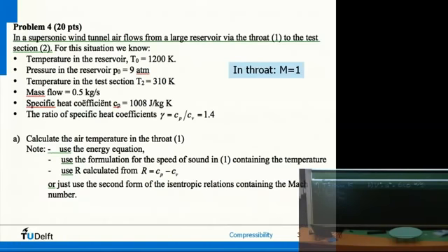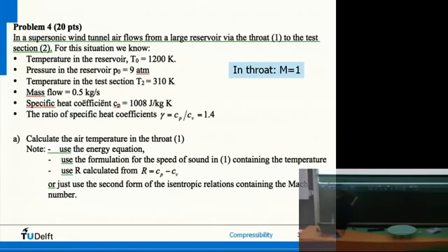Temperature. So we know the test temperature. What does that mean? What can we derive from that? Speed of sound. Perfect. A is square root of gamma RT, so we can derive the speed of sound. So that means this part we know. Now only V test. Any idea how we can find the speed in the test section?